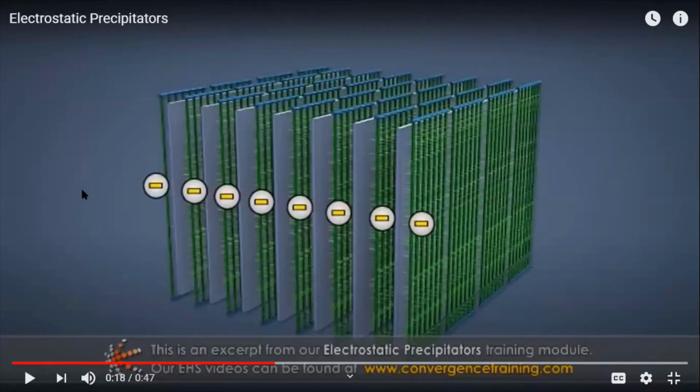The reason why it's negatively charged is because when you ionize the air, it's going to attract the positive ions to the needle, right? Those are oxygen positive ions, nitrogen positive ions. But the ions that charge the particles are going to be electrons. Electrons have a higher mobility and can charge the particles more efficiently. That's why people typically use negative high voltage for the corona needles, right? So basically we can generate more mobile charged species to achieve a higher collection efficiency.